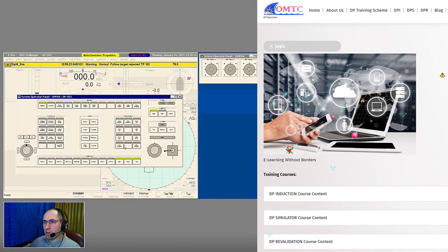Let's select thrusters first, as usual. We ensure that the control is taken to our panel. Then we have to select joystick mode and add DGPS number 1 as reference origin. As soon as the system is calibrated and taken by DP, we start the auto positioning mode.